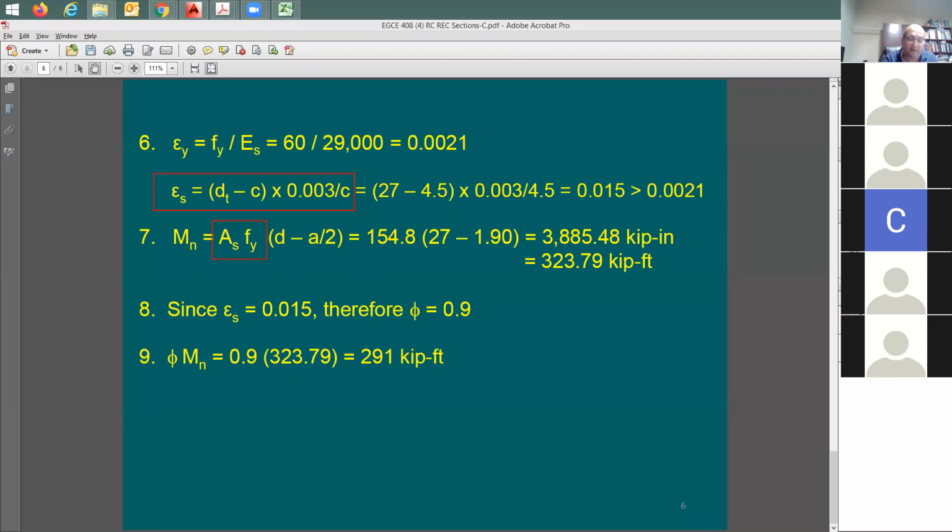It happens a lot that you look at the soils report or geotechnical report, and then he says that the soil is very corrosive. It has lots of chlorides. In this case, you'd like to use type 5. So you'd like to protect the foundation. So in this case, use stronger cement. So now you have an idea about the material properties in the concrete: what strength, what cement type. This is what you're going to be specifying in your design.